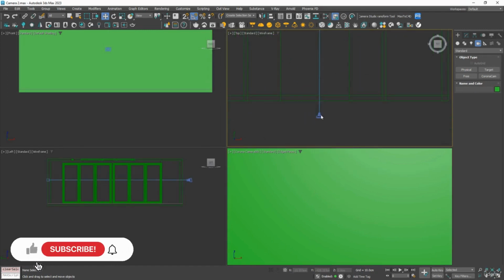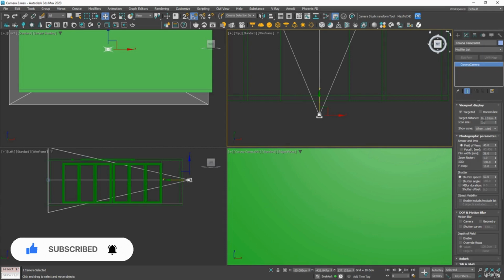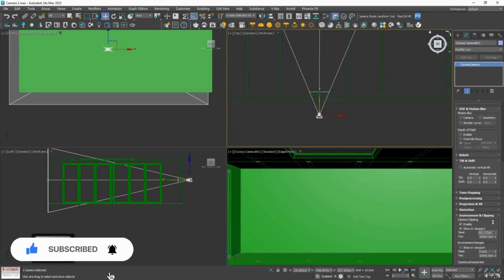So something we can do in a situation like this is select our camera, go to the modifier tab, and if you scroll down in here, you'll see environment and clipping. So we can enable that, and we can turn up this near. If you're ever turning up a dialog box and it's going really slow, you can actually hold Control and it's going to speed things up.